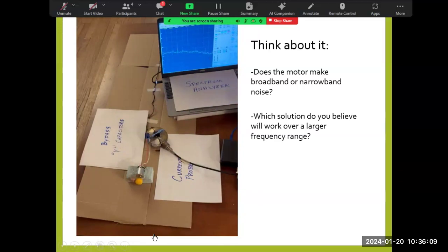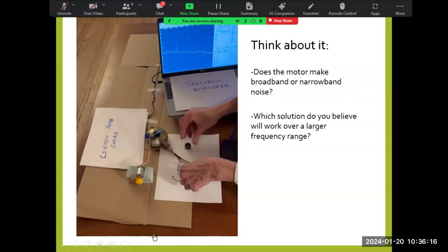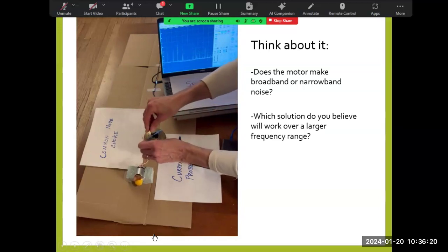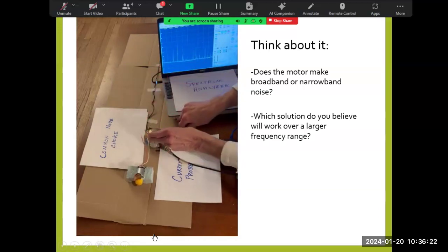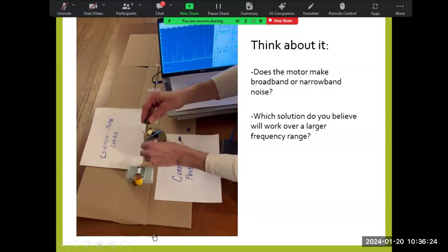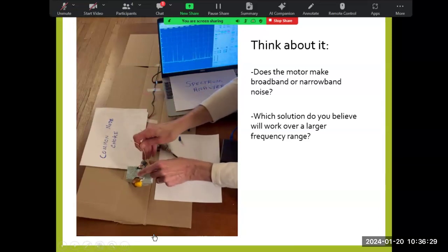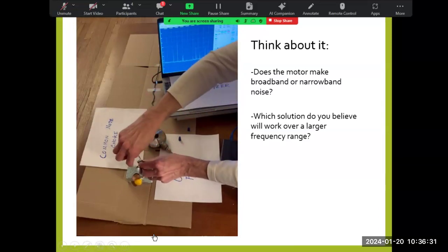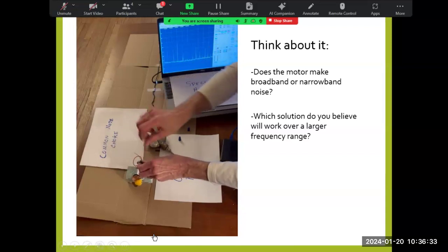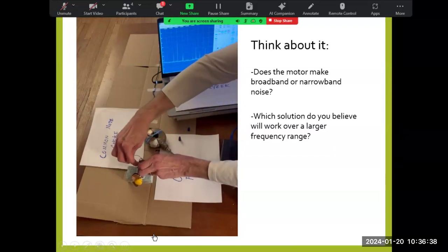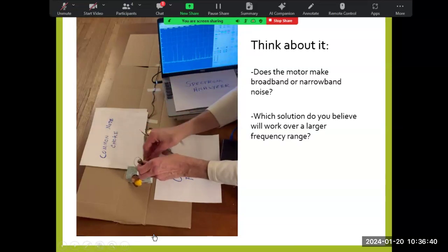See that? Now I'm going to add the common mode choke. I have to disconnect the wires to put that into the circuit. Okay. So off, the noise goes away. Put the core in. Both wires go through the core. You have to come back through the core. I loop it around so I have more than one turn. Then we have to connect it back up.